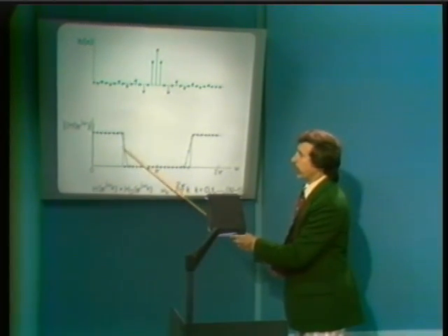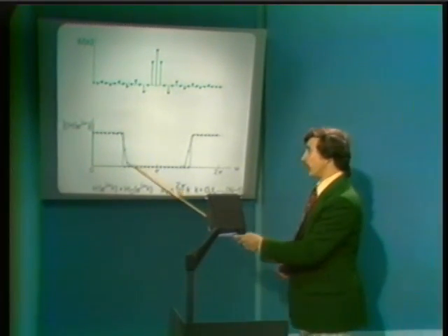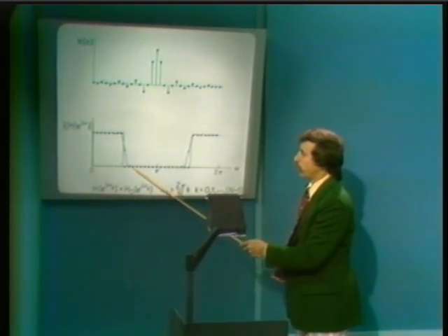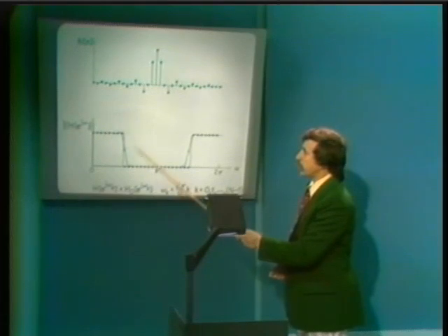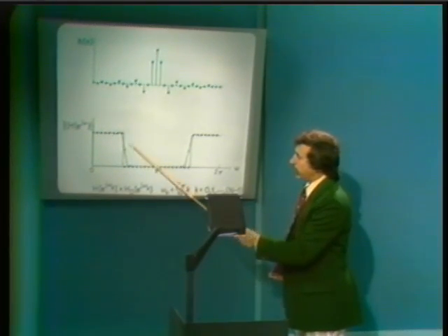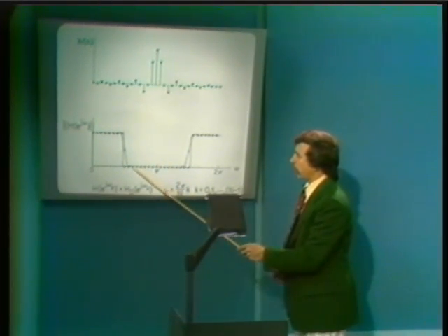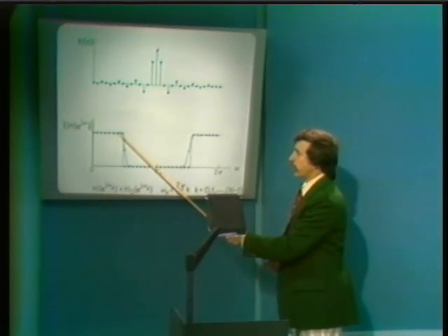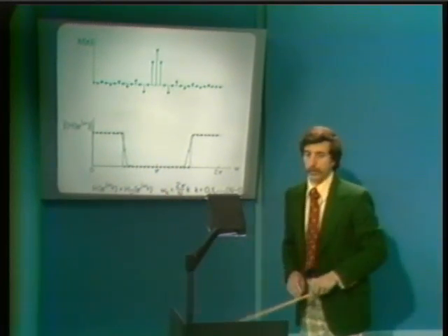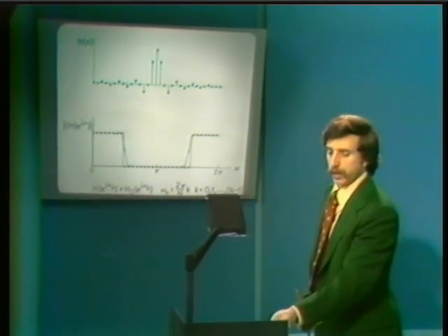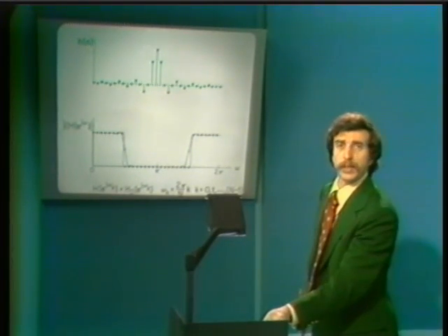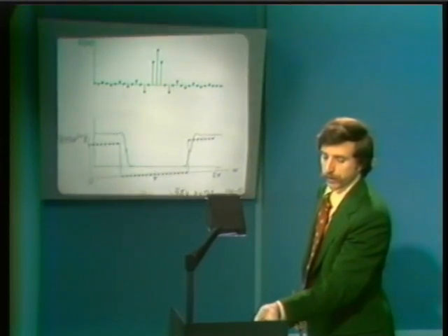And as we move this point up or down, then we will reduce the passband and the stop band ripple. We can also, of course, consider moving not just one point into the transition region, but 2 points or 3 points or more points. Obviously, as we do that, we will widen the transition band further, and at the same time, that offers some additional flexibility which permits us to reduce the passband and stop band ripple. So this then is basically the strategy in the frequency sampling method of digital filter design.